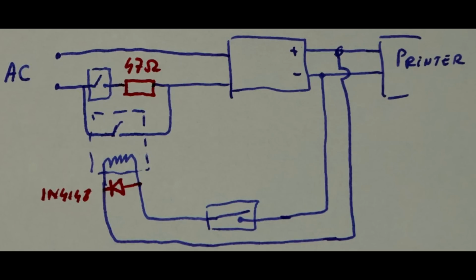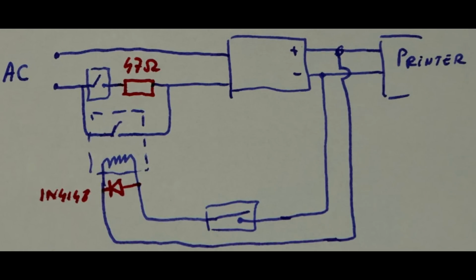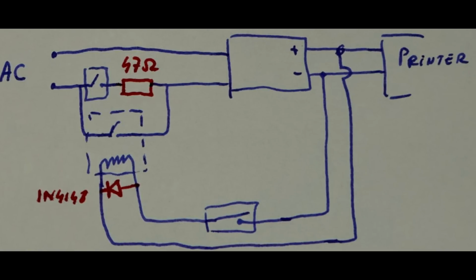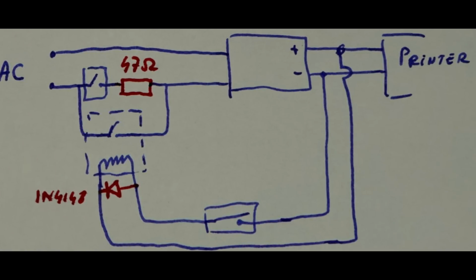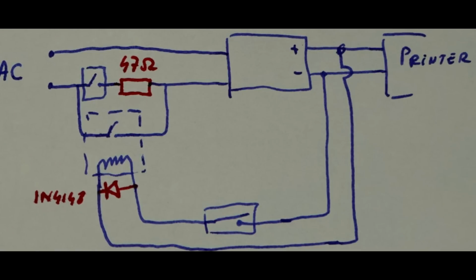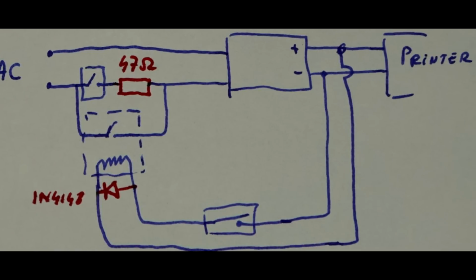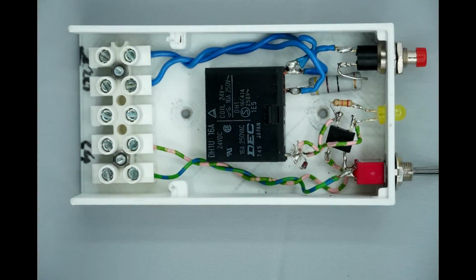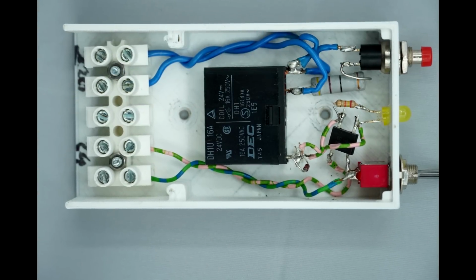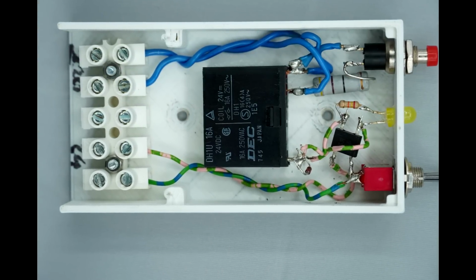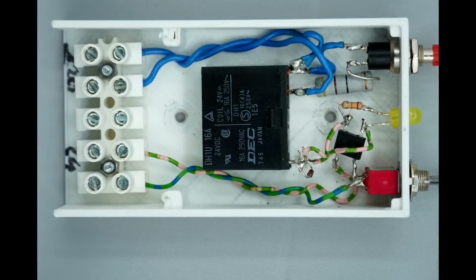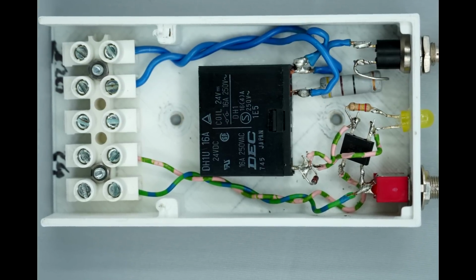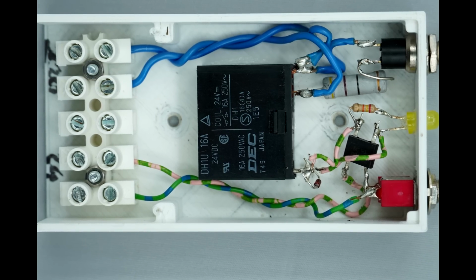And for the inrush current, I added a permanent 5-watt resistor, which I think is of carbon film type. The relay then clamps both the switch and this resistor, disconnecting them from the circuit. So this component only sees a large current and peak power during turn on. And the circuit has been working without any issue for the past year or so. These were not some complex additions, but they make the difference between a reliable and a non-functional circuit.